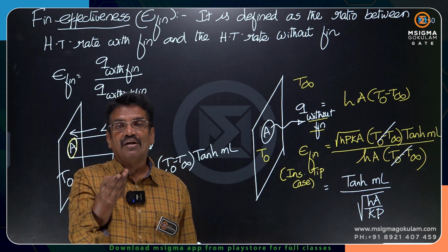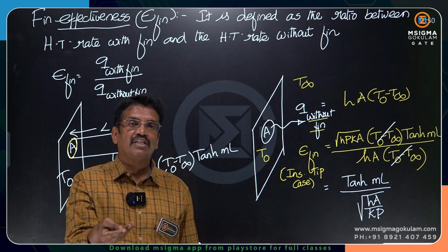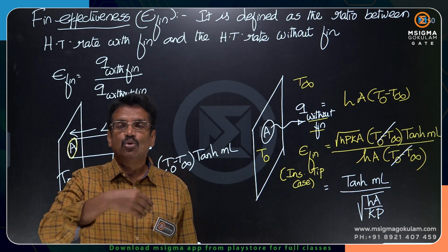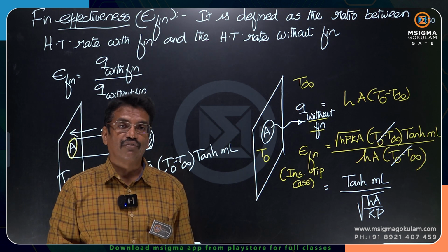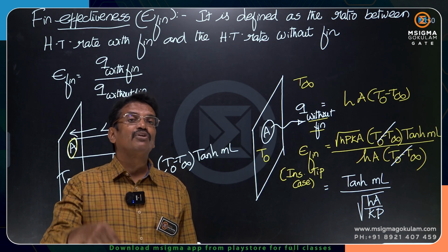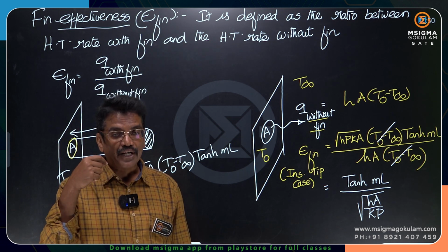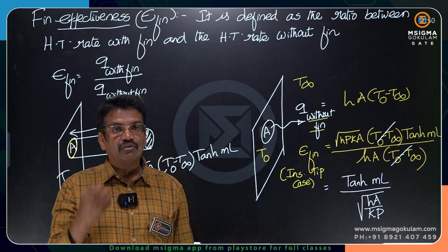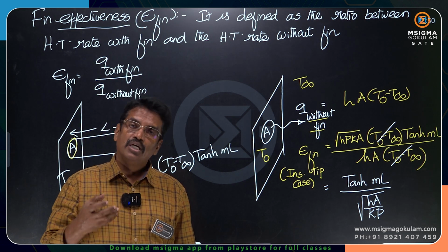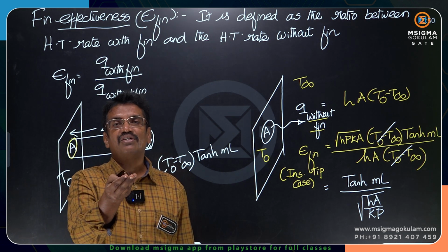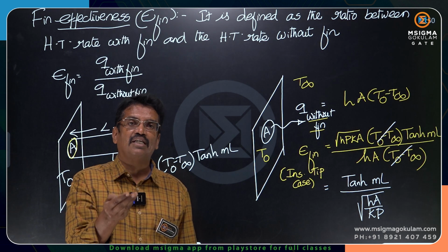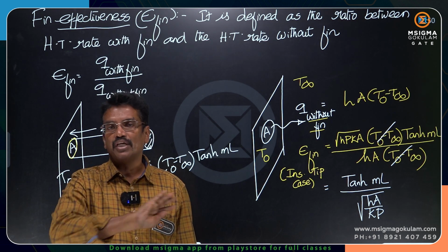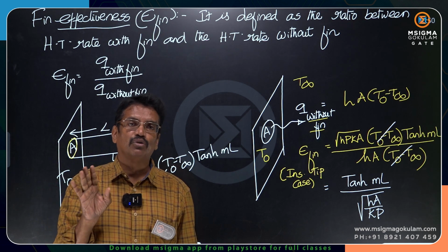If there is a meager 5% increase or 10% increase in heat transfer rate after keeping the fin, I can say that don't keep the fins. You run the show without the fins, because fins are money, fins are material, fins are extra design, extra component you are putting in. After spending so much effort, so much money, material, if you attach the fin, if you just get 5% or 10% increase in heat transfer rate, it is not worth keeping the fins. Don't keep the fins. You just run the show without the fins.